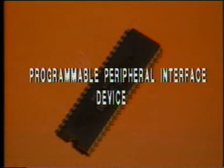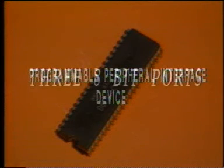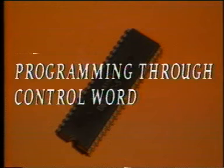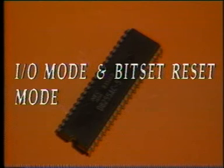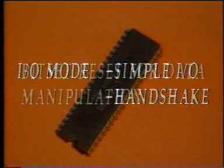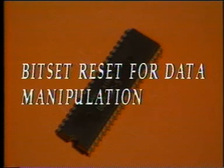Now let us review what we have learned in this lesson. The 8255 is a peripheral interface device which can be programmed. It offers 3 8-bit ports to the user. Programming is done by writing the control word into the control word register. It offers I/O mode and bit set reset mode. Under I/O mode, simple input-output interfacing as well as handshake data transfer is possible. Bit set reset mode is good for manipulating individual bits of data.